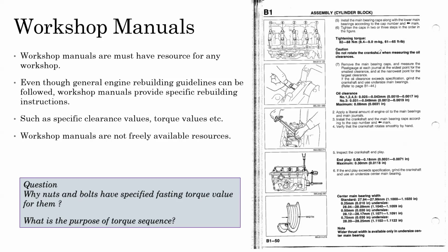So let's assume, for this task, we say this is 0.35, the exhaust valve clearance, 0.35 millimeters. That specific value is for that particular valve, right? But if you go for a vehicle such as a 4AG or something like a higher compression, high RPM engine, in such engines the valves are actually made of titanium mixed alloy. So titanium mixed alloy means they are not actually